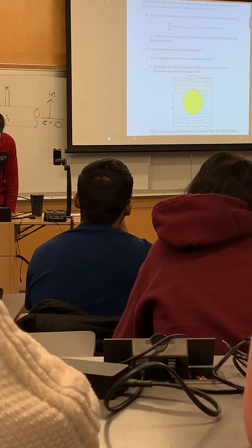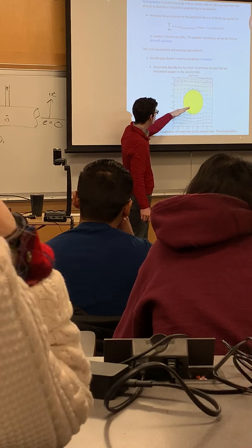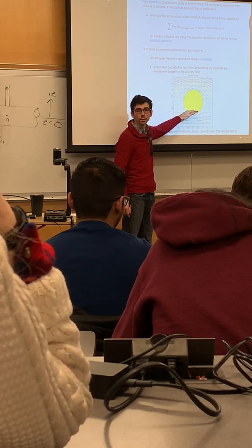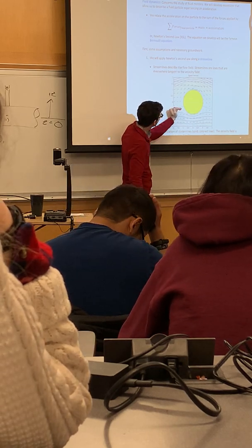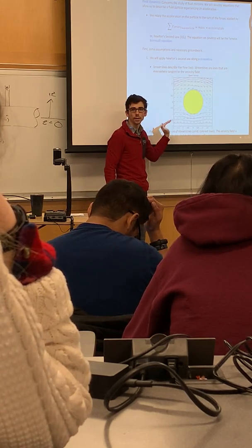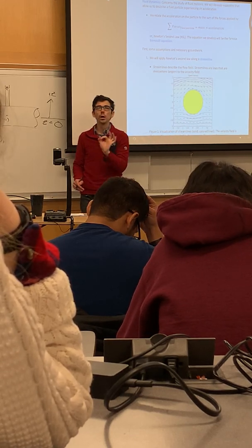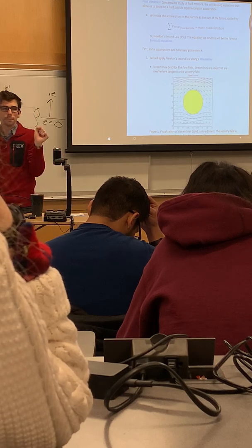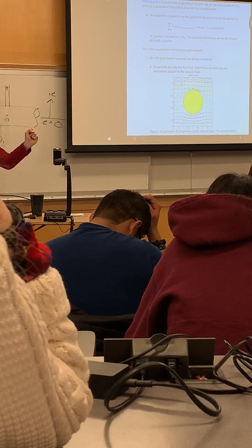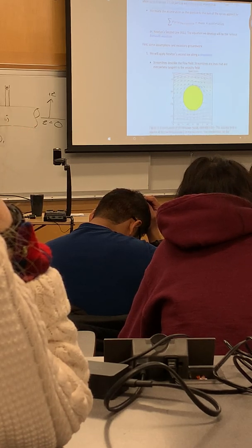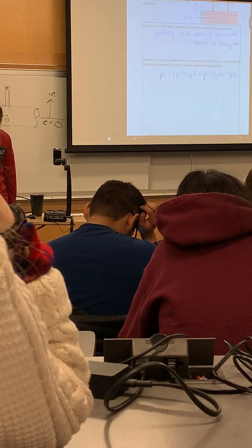So at that point, we end up with something similar to what would happen way back in our example here, right? In this image, there's a streamline that essentially dead ends on the object. There's no more velocity, it's not going anywhere. Other streamlines will do something in between. They'll deflect, they'll exchange some pressure for a change in velocity, but at one singular point for our analyses, we're taking there to be a point where all the velocity goes away and it gets changed over for pressure. Okay, good question.